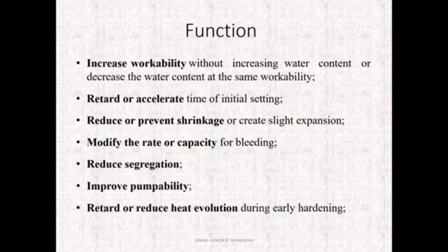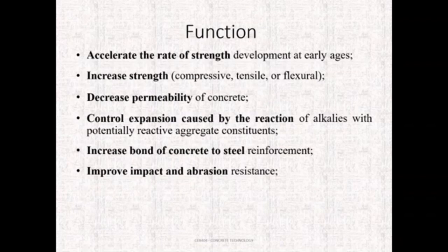The functions of the admixtures are: it increases the workability of the concrete without increasing the water content, or decreases the water content at the same workability. It accelerates the setting time of the concrete. It can be used to reduce or prevent the shrinkage during curing. It modifies the rate of bleeding. It reduces segregation, improves the pumpability, and it accelerates the early strength of the concrete and increases the flexural, tensile, and compressive strength of the concrete.